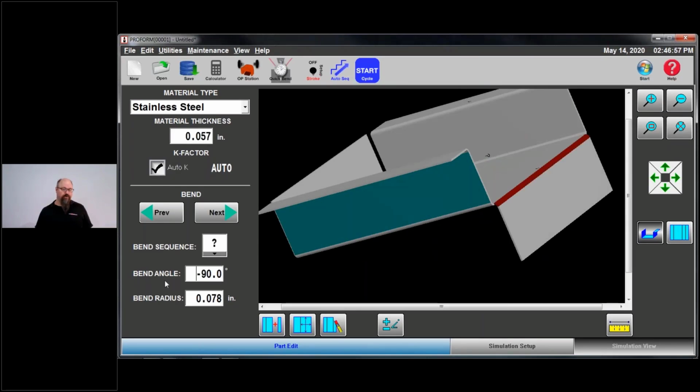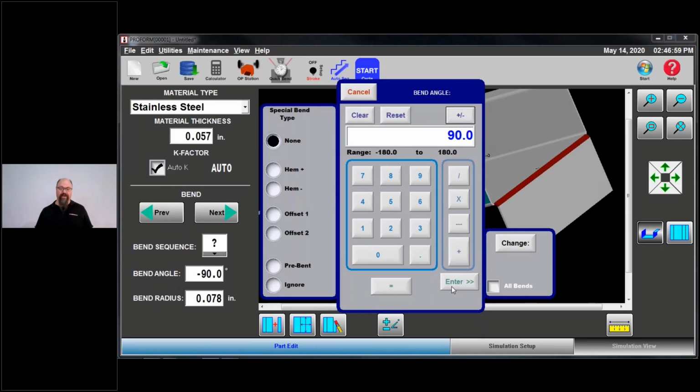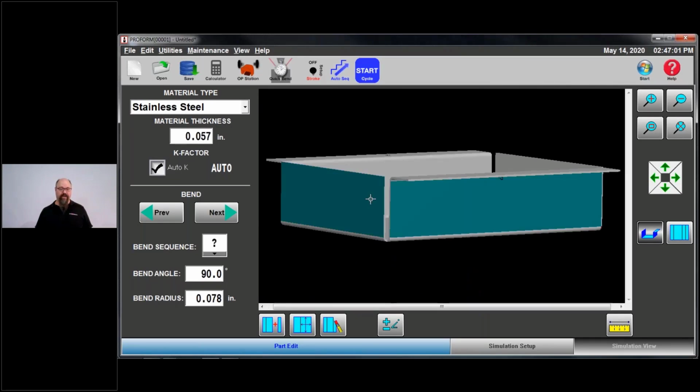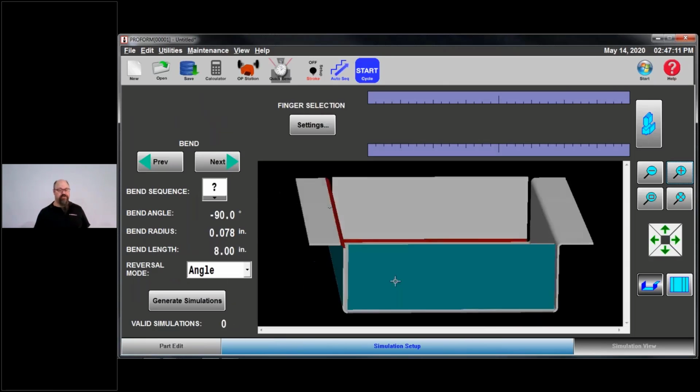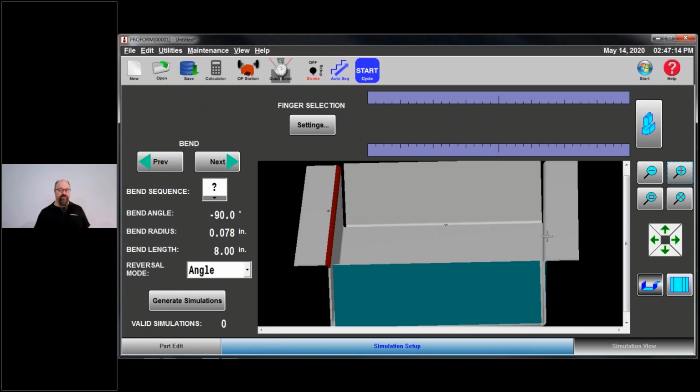Okay, so literally I've got a pan. I've got a pan with tabs on it. That's the only real advantage of the flat pattern. From here, you can go through the same way you did with the setup. You just now have to be worried about clearances between the sides on the last 2 bends. Like with any pan, you have tool clearances.